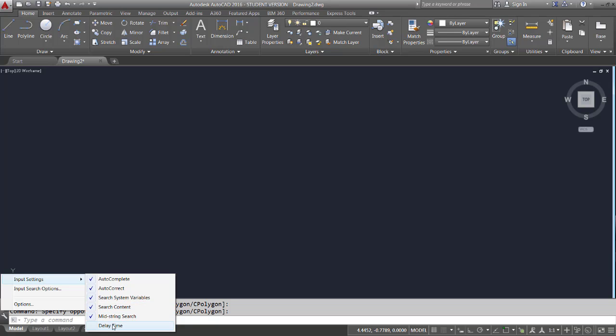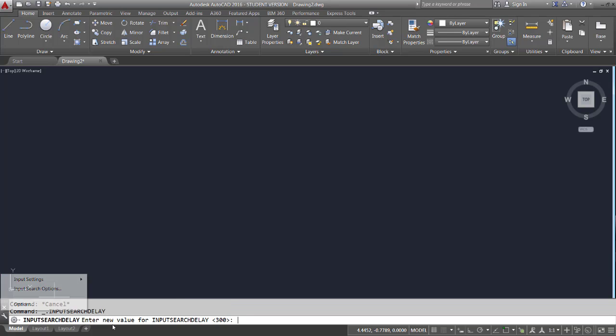What I'm going to do is I'll leave that on, but I'm going to change the delay time. So the default delay is 300 milliseconds. I'm going to change that to something like, let's say, maybe 1200 milliseconds. So I'll type in 1200 and hit Enter on the keyboard. And that gives me the input, puts the command into AutoCAD. And so that's what's now set on our screen. So we won't have that in the way as we're trying to demonstrate things. So I've got all my controls, my drawing aids set up, turned off rather.